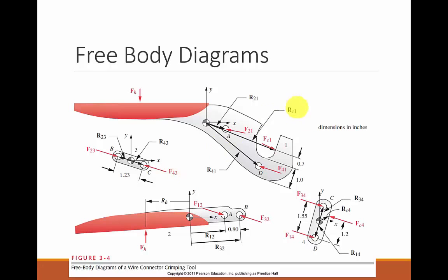Another first thing to notice is that we're going to put a center of gravity in each element. Each element has its own center of gravity, and each element has its own coordinate system that comes from that center of gravity. So now we have our R's calculated in terms of I, J, and K. In this problem, we're only really doing a 2D analysis, so we're going to say everything is happening when K equals 0, or when Z equals 0 in the K direction. Okay?